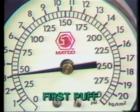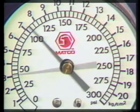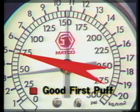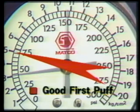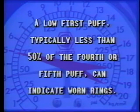Observing the first puff during a compression test can give us very useful diagnostic information about cylinder seal. Small leaks, such as those found with worn piston rings or light cylinder wall scoring, will not produce high compression on the first compression cycle, but will produce satisfactory results on subsequent cycles due to increased cylinder sealing efficiency caused by increased RPM and hydraulic sealing, overcoming the slight leakage. A low first puff, typically less than 50% of the fourth or fifth puff, can indicate worn rings.